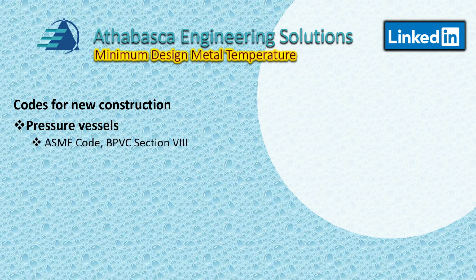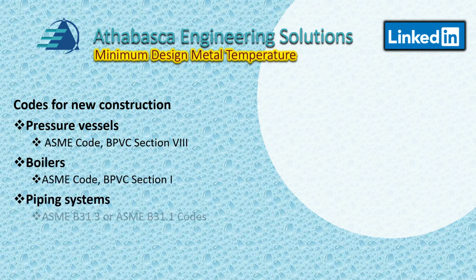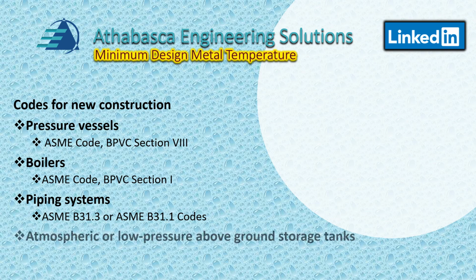So for pressure vessels, we have the ASME pressure vessel code Section 8, Division 1, 2, and 3. We have the boiler codes. We have the piping codes, for example B31.3, one of the most common ones, and B31.1, and there are other codes like B31.4, and of course the pipeline codes.